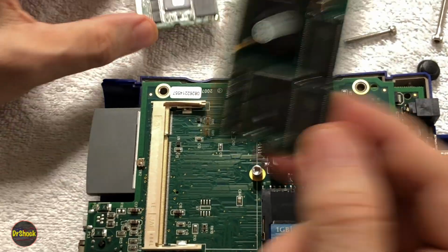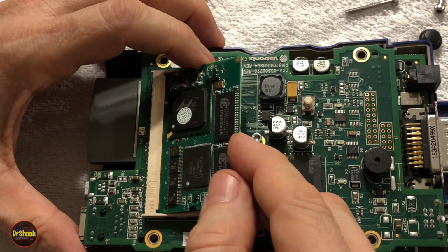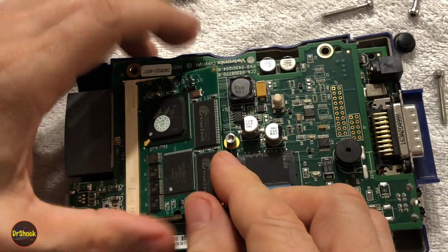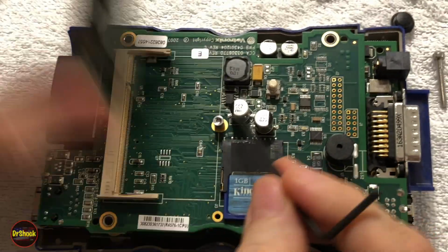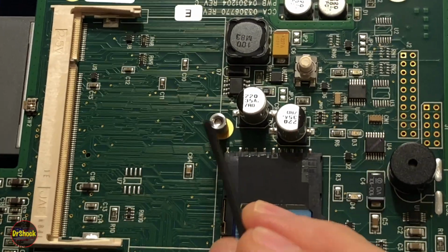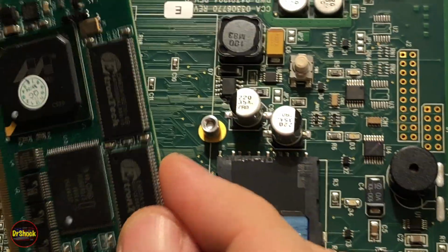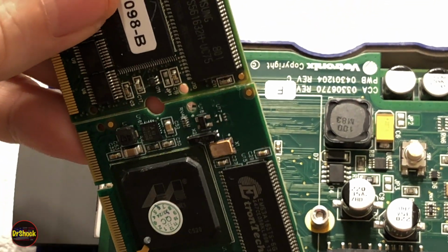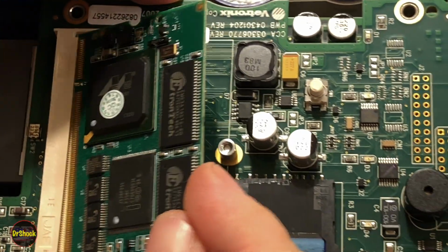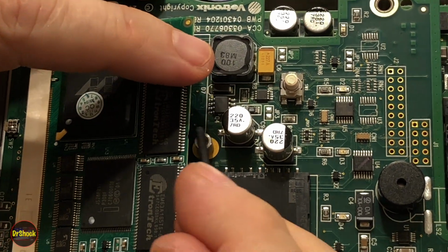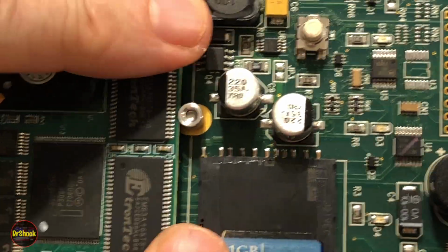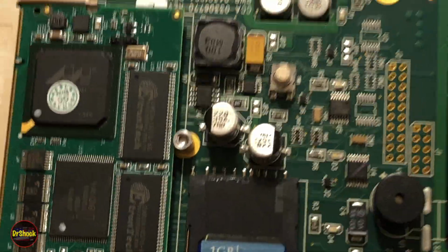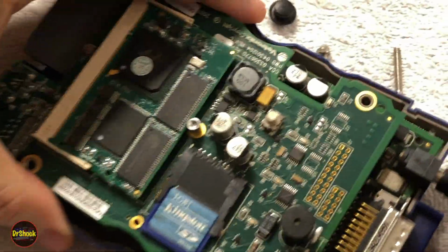In fact, I believe the top quality clones, and I've done a review on these in the past, are absolutely perfect substitutes to the real ones. Now, what you have to do, though, is a real MDI is going to have this stud here in the way. And so you'll notice that these are slightly taller by just a millimeter. And so what you'll end up having to do, what I'm doing now, is you have to file a little tiny notch in there so that it'll clear that stud and you can actually get it to fit in there. All right, let's see what this guy does with a new board.